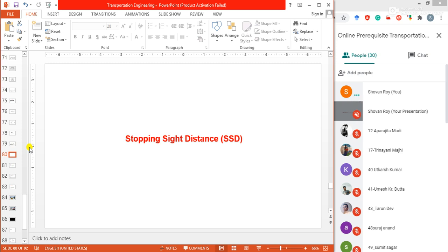Am I clear? Headlight sight distance is another sight distance considered by the IRC after intermediate sight distance. This is the distance visible to the driver during night driving under the illumination of the vehicle headlights. This sight distance is critical at upgrades and the ascending stage of valley curves.